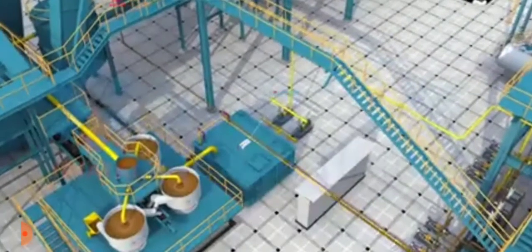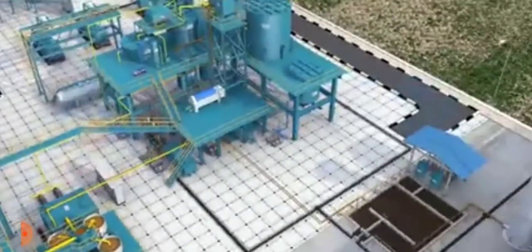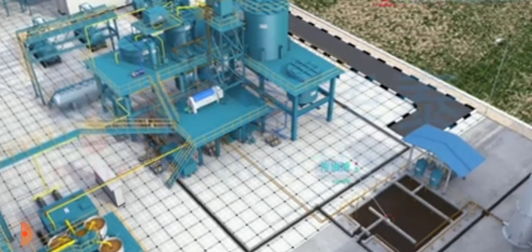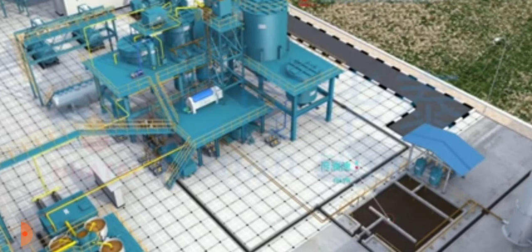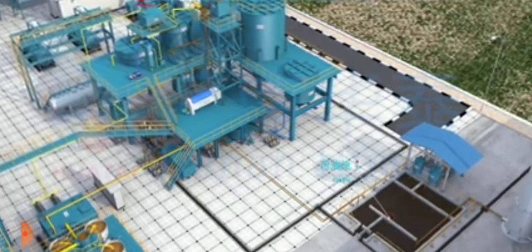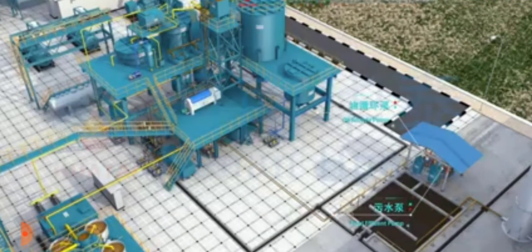Oil is recycled and conveyed into the crude oil tank. Oil residue and water are collected into the fat pit for settling separation. The fat pit collects all dirty oil and water in the production plant and separates them into dirty oil and water. Dirty oil is conveyed to the crude oil tank by the oil circulation pump. Dirty water is conveyed to the dirty oil pit by the effluent pump.